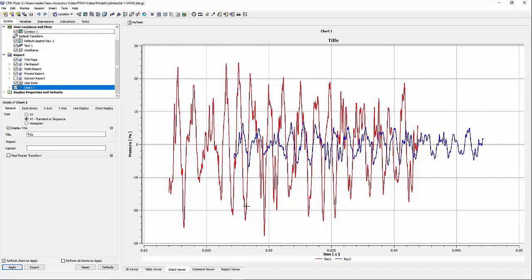After plotting the pressure fluctuation data that was received at the location of receivers 1 and 2, we can see that there is a lag between these 2 signals that is equivalent to the time that the pressure signal has to travel to reach receiver 2's location. And also you can see the attenuation of the signal due to the distance that was traveled.